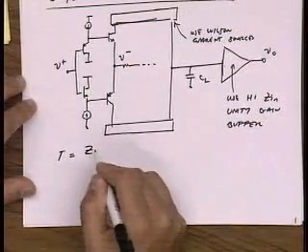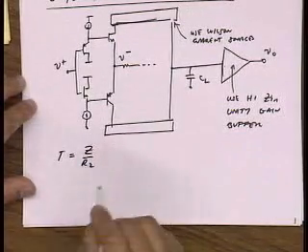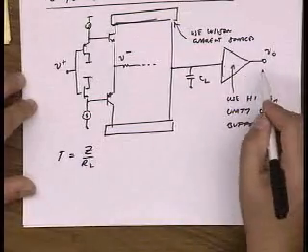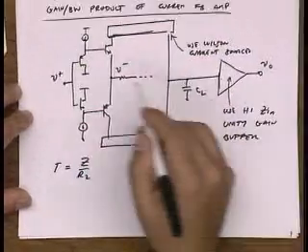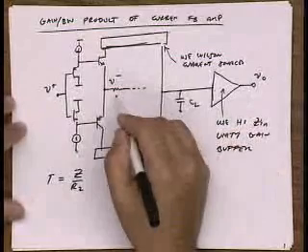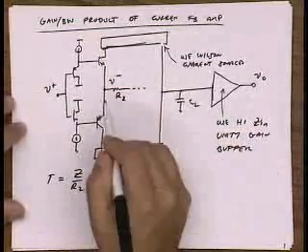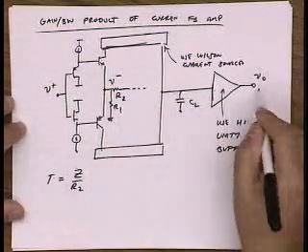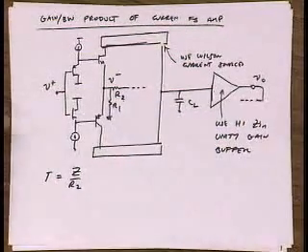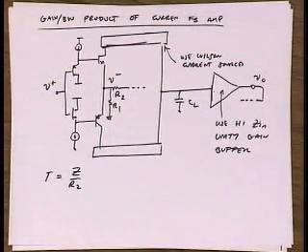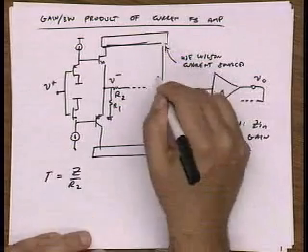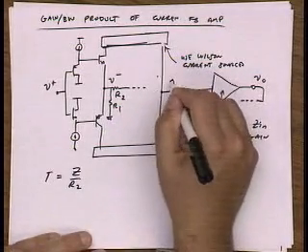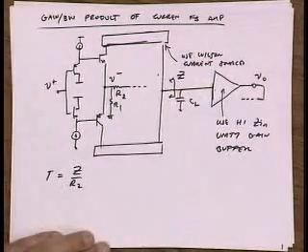All right. So last lecture we calculated the loop gain of this, and we found that the loop gain is Z over R2, where R2 is basically this resistor. So in a feedback configuration, we would have R2 and R1. And Z is the impedance of this node, the impedance looking here, including this capacitor, obviously.